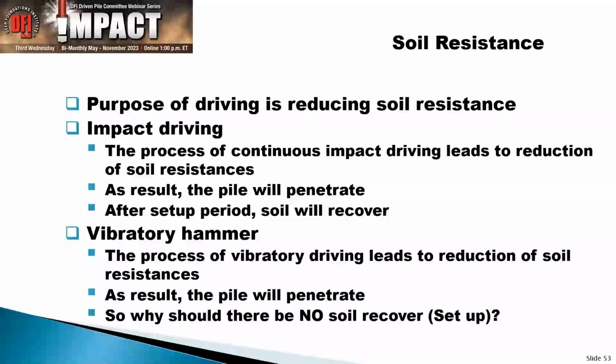Vibratory driving, we're not using, and that's a misnomer, vibratory driving. A lot of people think that we are liquefying the soil at the bottom. That is not necessarily the case, but the vibratory action does allow the pile to penetrate, and the question is then, why would there not be a soil setup?